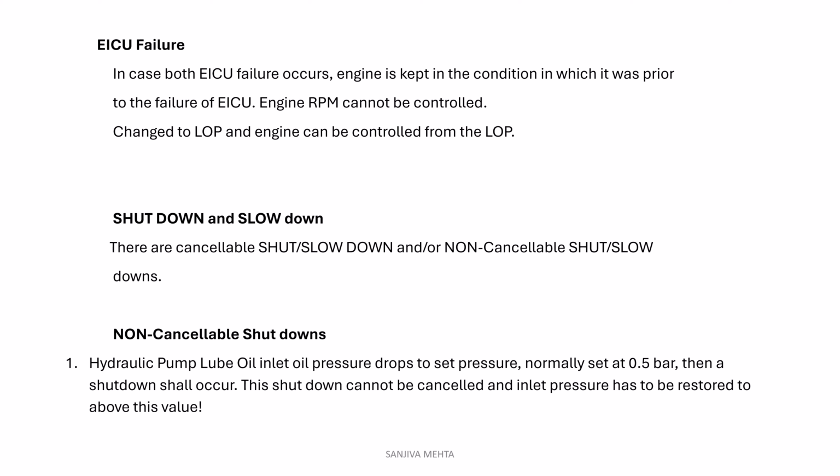And inlet pressure has to be restored above this value. Make sure your supply main lube oil pump is running and supplying the pressure, the filter is not choked and all. Then only this alarm, this shutdown will go away.